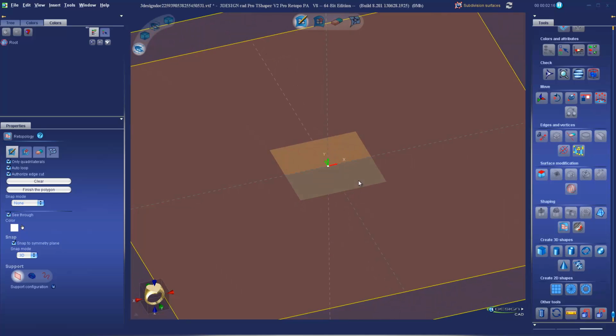Any retopology you do is going to be done on a support object, and we'll talk about those. We have 4 tabs inside retopology for the tool. And down here underneath, we have the settings for setting up our support object. We can place it on a plane, a solid, or a curve. We're going to cover solid and curves when we go into our jewelry projects. For now, we'll just do a plane.